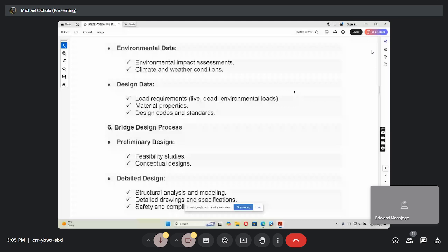Material property is very important. I've told you for bridges, you just need to be aware if it is reinforced, you have concrete, and the grade of concrete varies depending on the exposure. A structure which is exposed to chemicals has to be enhanced. There could be needs for admixtures, chemical resistive properties need to be enhanced to take care of the contaminated state of the soil contact. You need to be aware of all that.